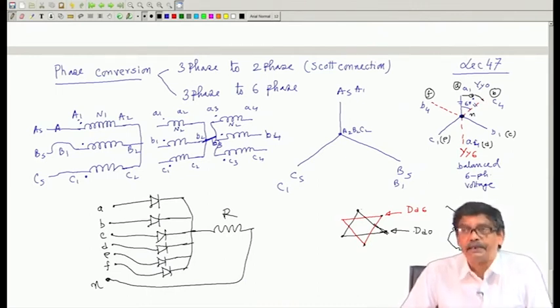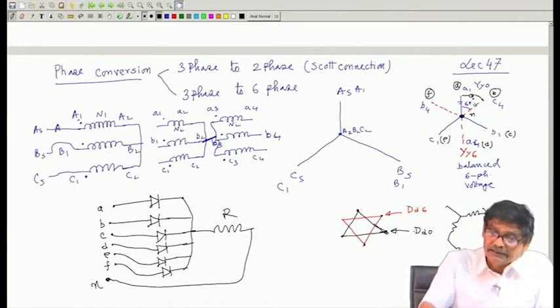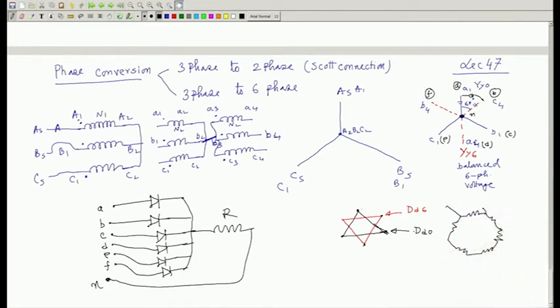and balanced 6 phase voltage you have been able to apply. Anyway, see, this 3 phase transformer connection is a very nice subject, and a lot of further connections are there, using many small windings, adding that phasors. For example, one of such examples was the traditional zigzag connection, as I told you.